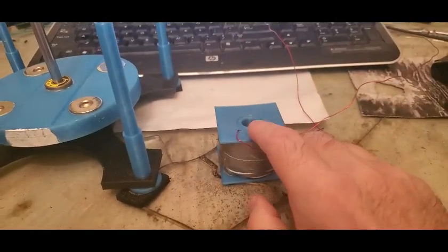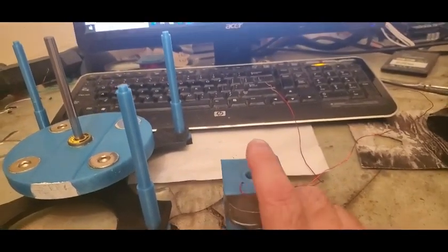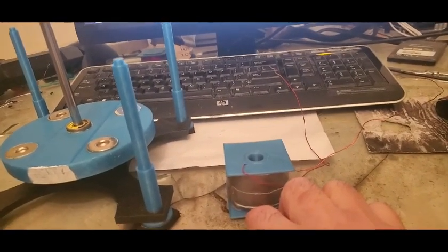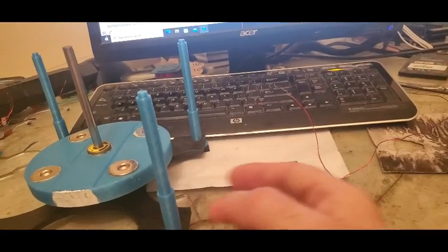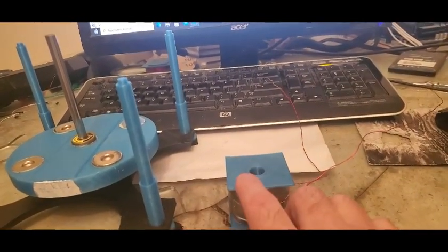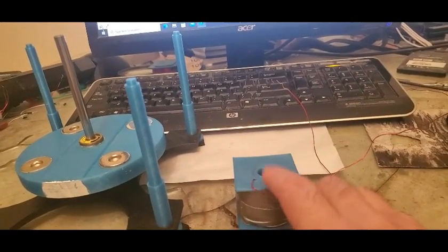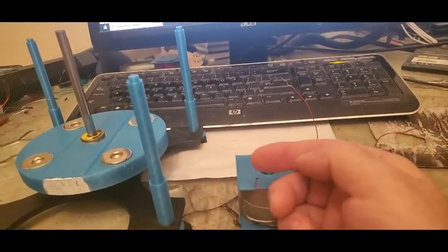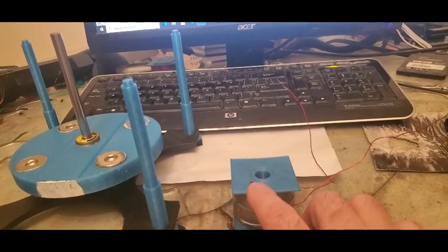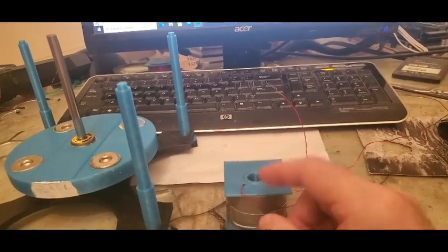Now, when you pulse it, it's going to happen in 1/100th of a second or quicker, but let's be silly and say it's a 10-second pulse. For 10 seconds this is increasing in current, and there's nothing you can do with that changing magnetic flux. But when it collapses, the current being produced, the inductive spike, is of opposite polarity than what you're putting in. So you can grab that, and you need to rectify it. How would you rectify it? That's where a diode comes in.